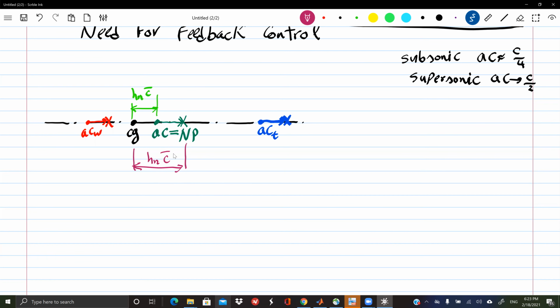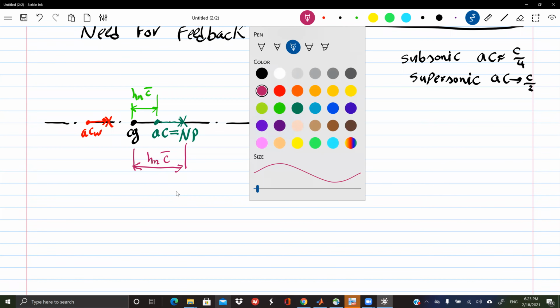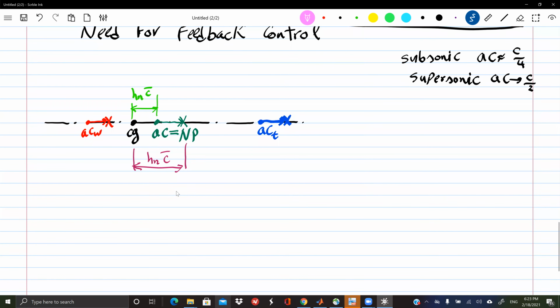So this is not acceptable, that a fighter airplane, which is supposed to be maneuverable, in its operating condition, the supersonic, becomes crippling to the pilot, right? So what's the solution? Well, the solution is, let's move this guy here so that in the supersonic regime, it's that small and acceptable static margin.